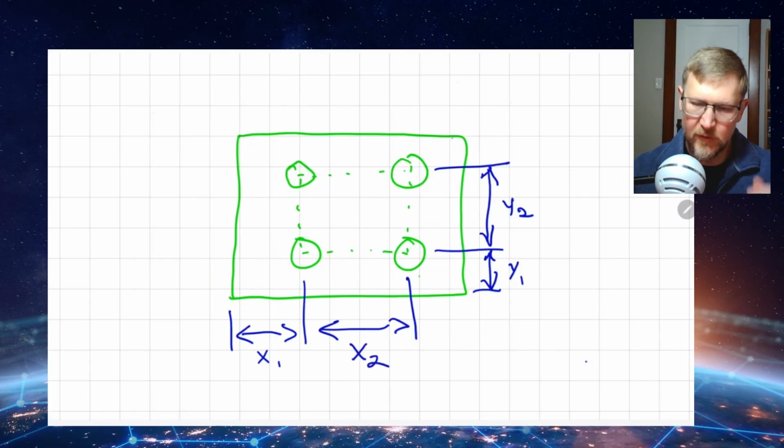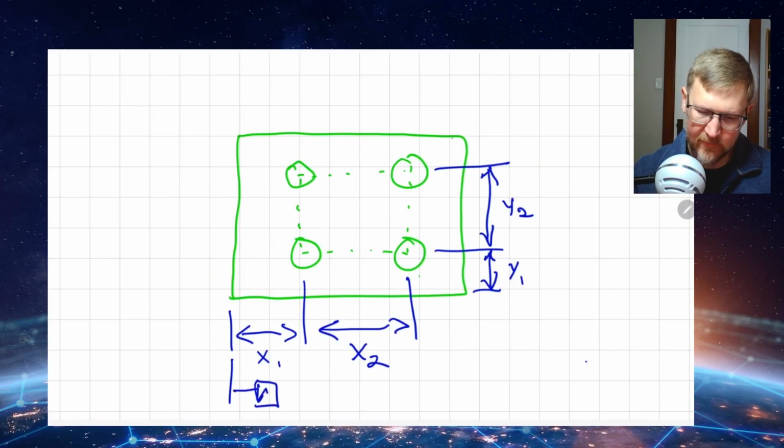So when you're doing this, you have some play that you can decide in terms of the tolerances. Now, normally, of course, chain dimensioning can be a tolerance stack-up issue. So if you wanted to locate these relative to, let's say this is datum A, right? If you wanted to locate these relative to that face, well, that's one thing versus locating them relative to each other.